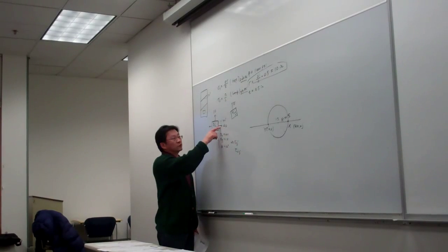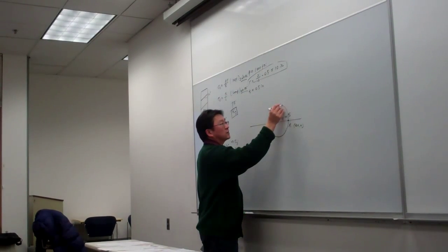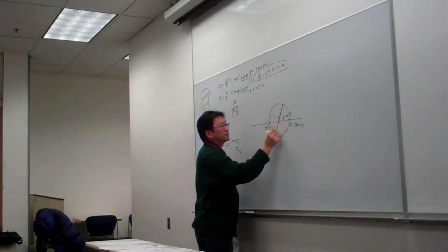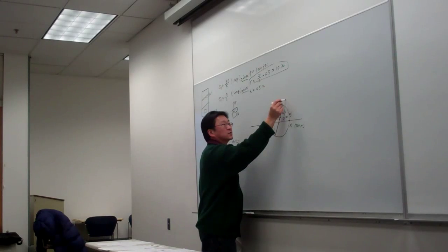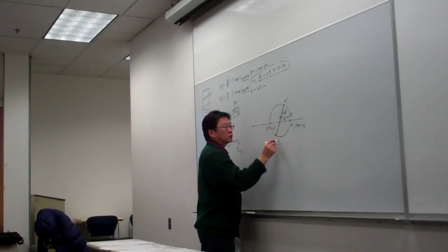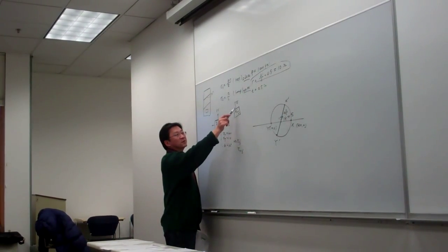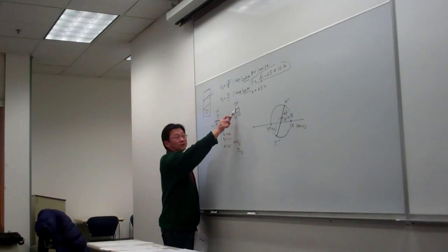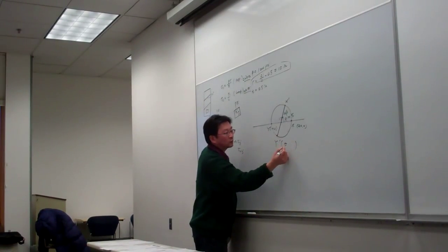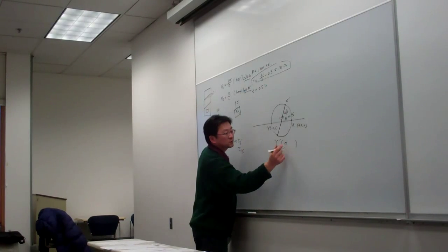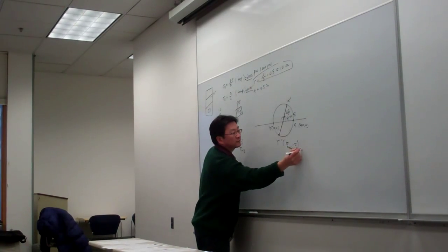Okay, and now again, we rotate counterclockwise 30 degrees, so on the Mohr circle that is 60 degrees. So we rotate into here. That is, we rotate by 2 beta angle. So this is X prime, this is Y prime. Right now we already identify that the information on the welding surface corresponds to the Y prime plane. So here we have to look for the coordinate for Y prime. This will be our sigma normal to the welding. And this will be the tau, and again that is on the welding.